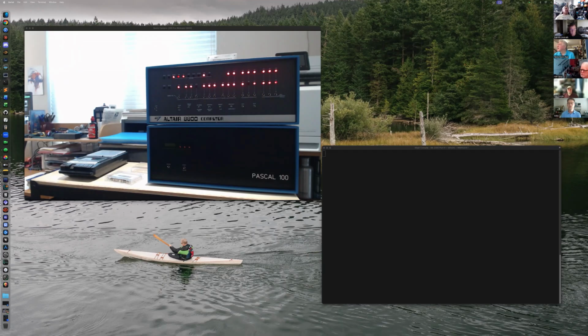But anyway, yes, we have a SIO replacement. Nice. Good job, Patrick. Seems to work well. So this is the SIO board where the interrupts don't work. And dummy me, some of these other UARTs need that minus 12 volts to work, so it didn't have that. Boards are coming that are supposed to fix all that, and then we'll see.